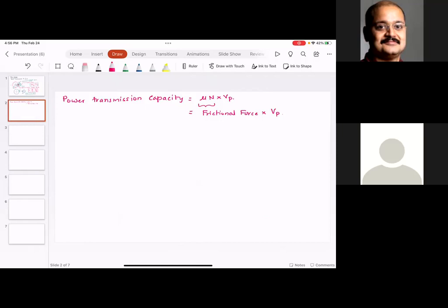If you don't believe me, put mud in your washer and tell me what happens. After some time, the washer would break down. Worse, put some concrete in your washer and see that it would break down after a couple of cycles. Exactly the same thing is going to happen with the pump, either reciprocating or rotary. Pumps are for fluids, for liquids. Pumps are not for semi-liquids or contaminated stuff. The design process for pumping contaminated water or wastewater, called black water or blue water, is completely different.